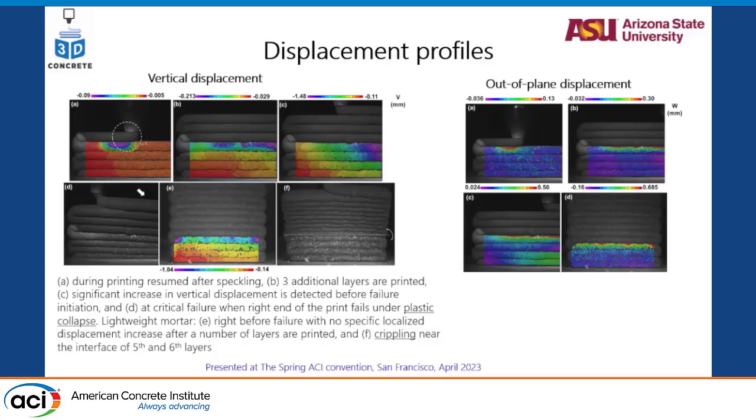I do not have that here, but again, there's more detail to it, like how the analysis was done, but the predictions were quite close. So whatever we predicted as a plastic failure through the analytical model, we saw that through DIC it was a plastic failure, while something that was more of a buckling type, with out of plane displacement, was a buckling kind of failure.